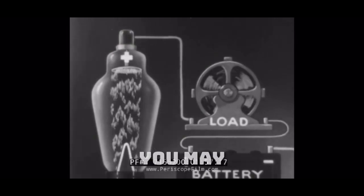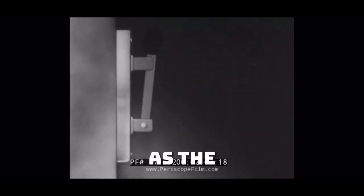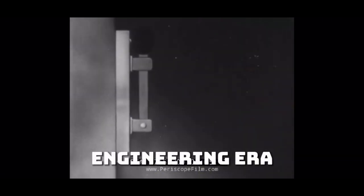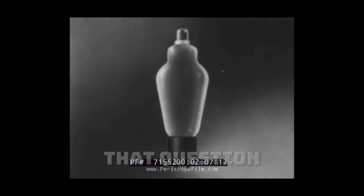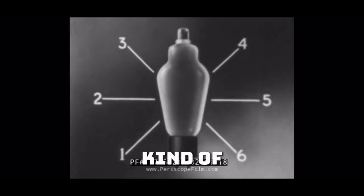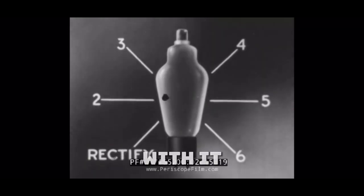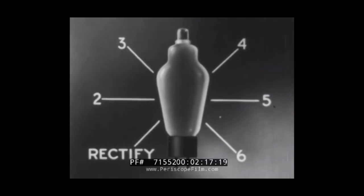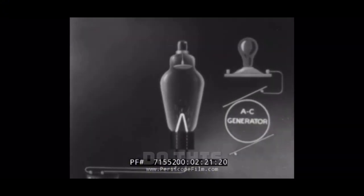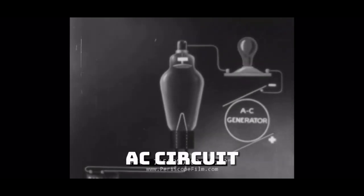Now, at this point, you may ask, if an electronic tube is basically just a form of switch, why is electronics hailed today as the technique of a new engineering era? To answer that question, let's review some of the basic things that we can do with this new kind of switch. In the first place, we can rectify current with it, converting AC to DC. We can do this merely by connecting an electronic tube in series with an AC circuit.